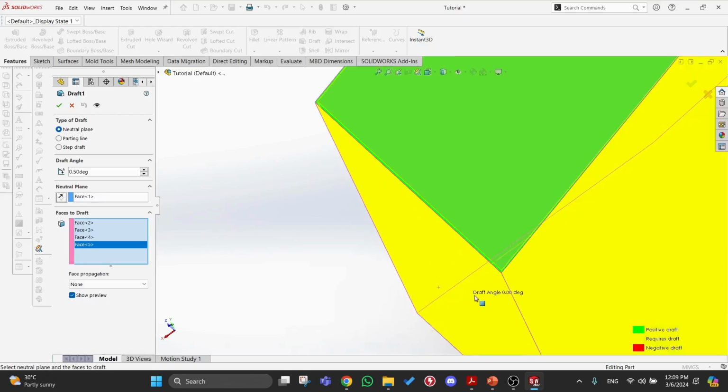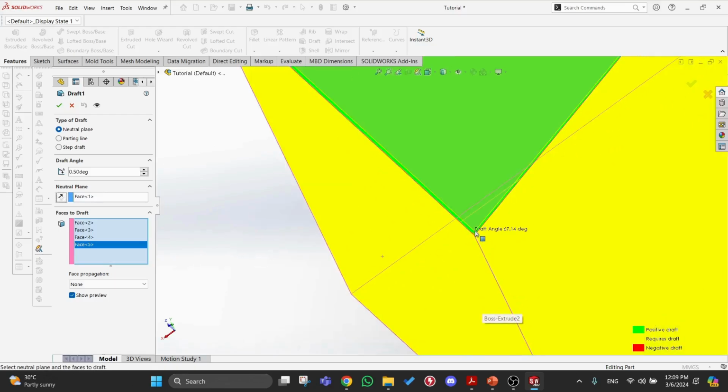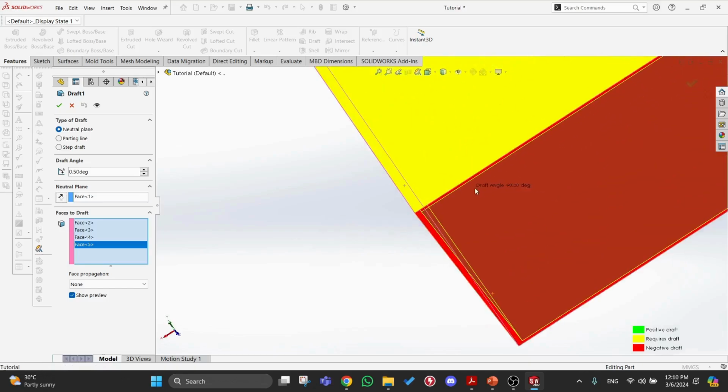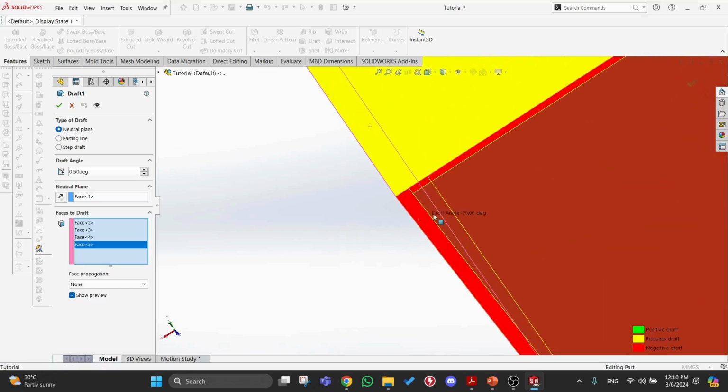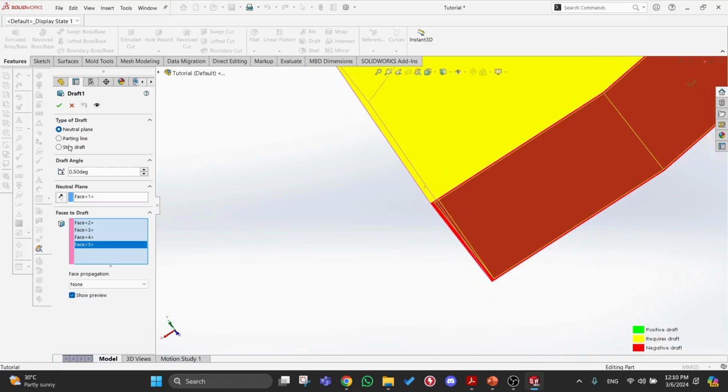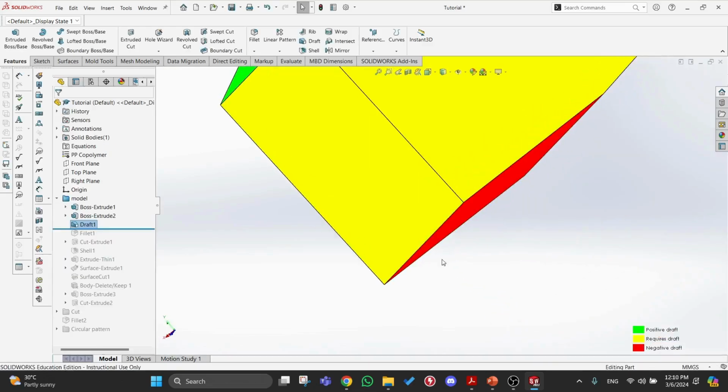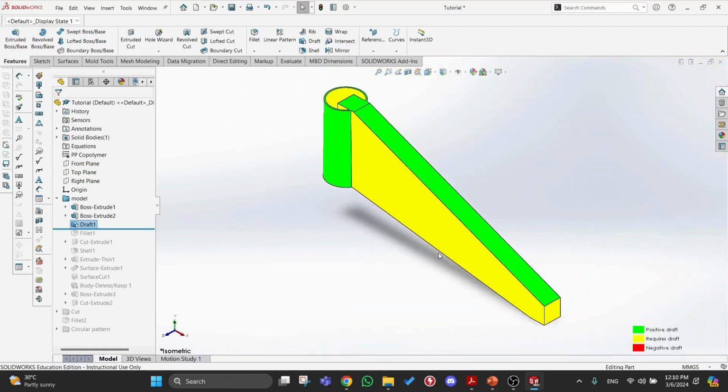Even if it cuts in here, you can see it cuts in, yes, correct. However, the bottom side, it also cuts in a bit. So why is this bad? This is bad because once it cuts in like that, it chips off maybe a few millimeters off of your dimensions, and that is not the specifications required by your client or the lecturer.